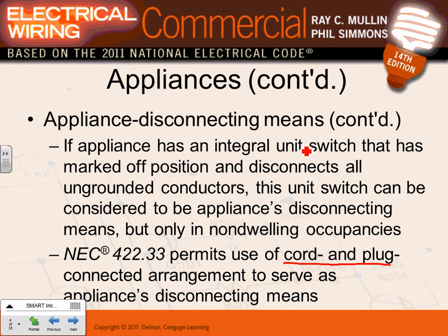So when it comes to appliances, what I want to emphasize is you need an overcurrent protection device tied to a branch circuit that feeds the appliances, and you need some type of disconnect to disconnect these appliances. That could be a snap switch, that could be the plug itself, that could be a big NEMA on the wall disconnect, that could be the circuit breaker if it's within sight, like we did with the water heater, if you guys remember. So these are the things to focus on.